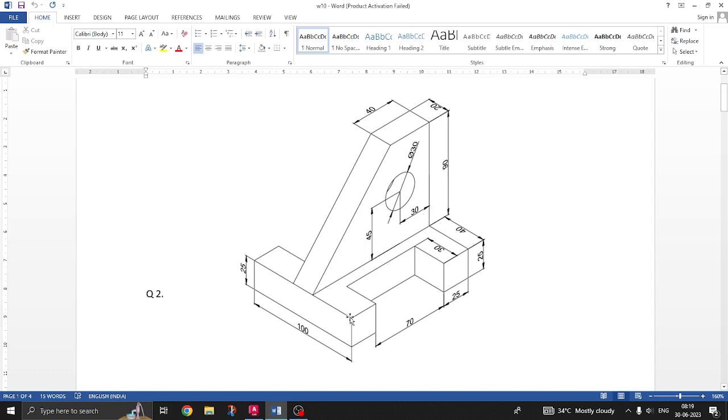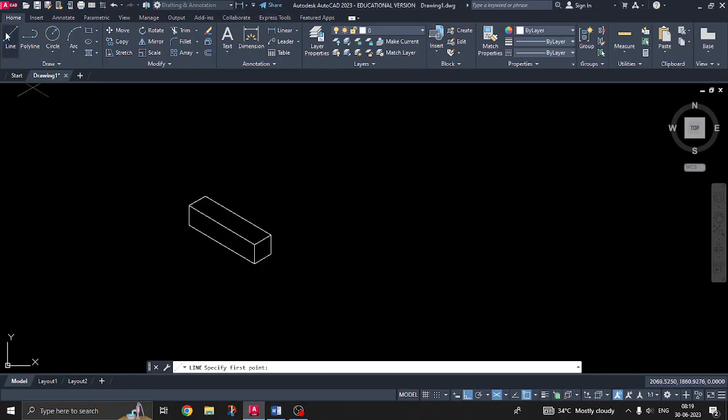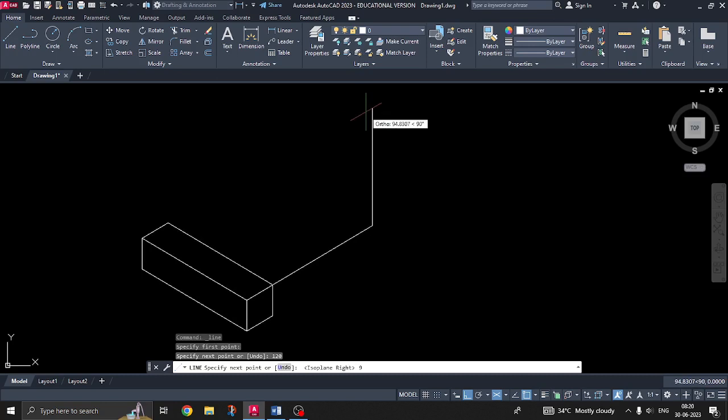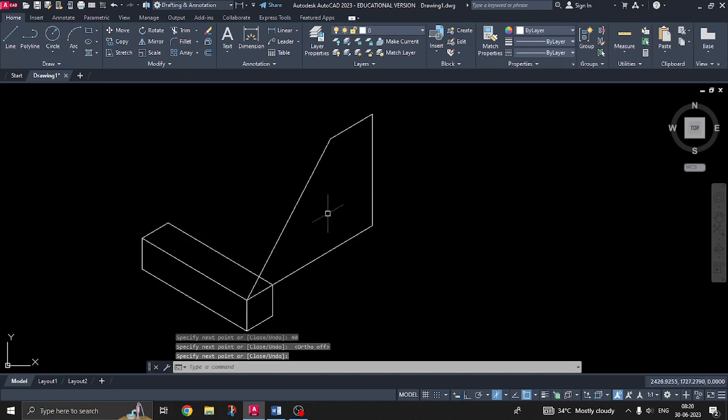Okay, wherever you want you can draw this corner. We will draw this corner. Thereafter we will move on to 40 mm this direction. Okay, so that let us take line, select from here, 120, above ISO plane. Okay, 90, this one is 40, and switch off ortho. In order to draw the inclined line, switch off ortho, F8. Okay, and join. Okay, understand?